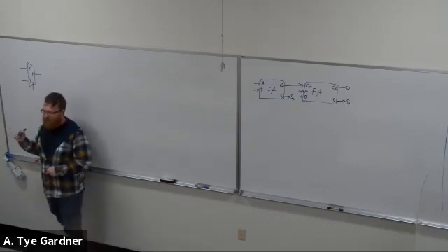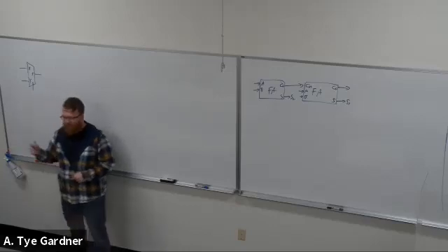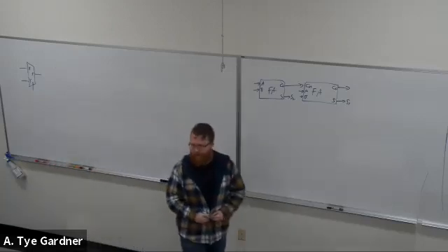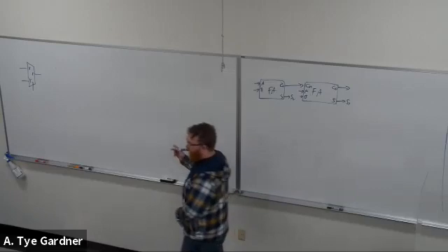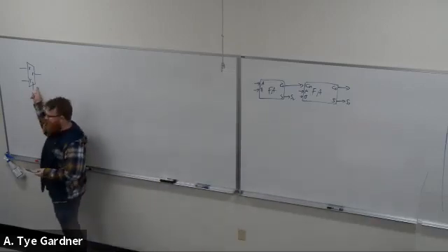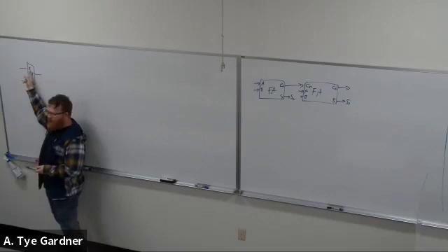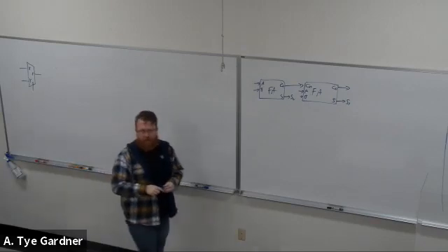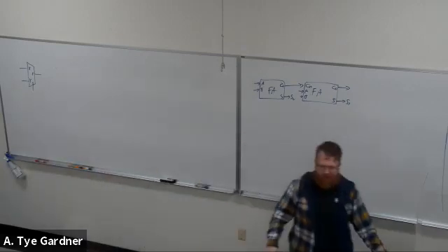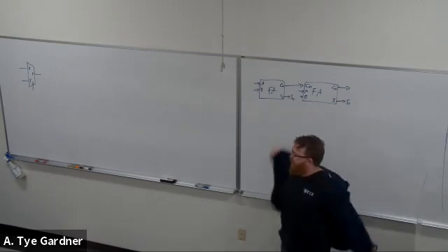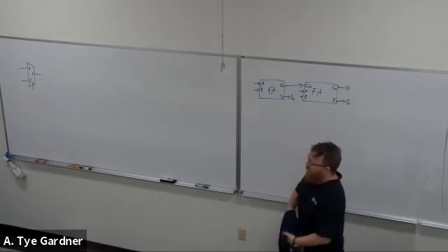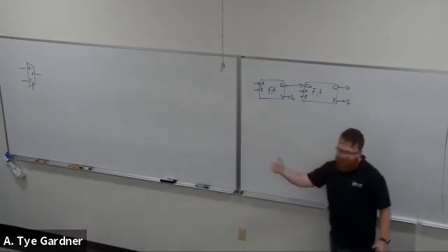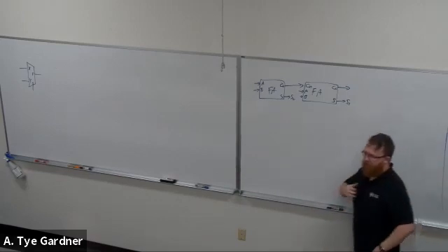2-input muxes. Okay. So you know how we've done a 4-input AND gate from 2-input AND gates? We're going to do the same thing, but with muxes. Now, muxes are important. All they do is if the select line is 0, it takes the X inputs. If the select line is 1, it takes the Y inputs, right? This is controlling what we call the data path, which we will get to in more detail later. But basically what that is saying is that I can have one of 2 inputs and we're going to put it to the output. We want to select which input we're putting into the output, right?